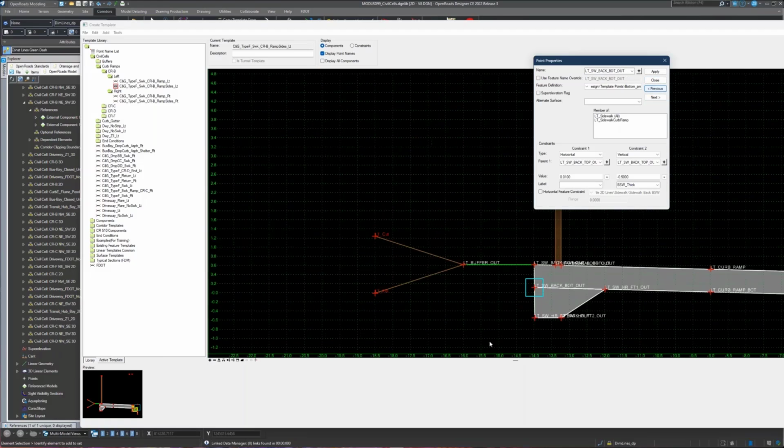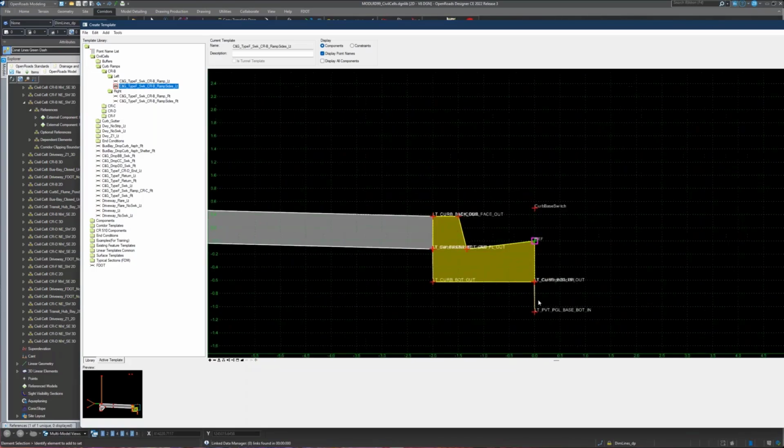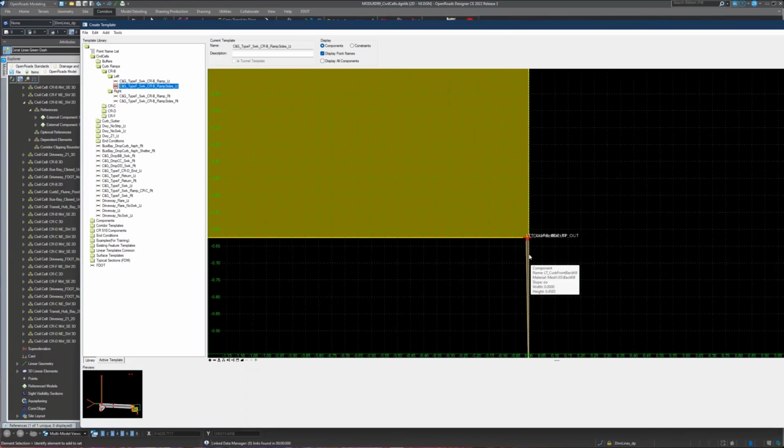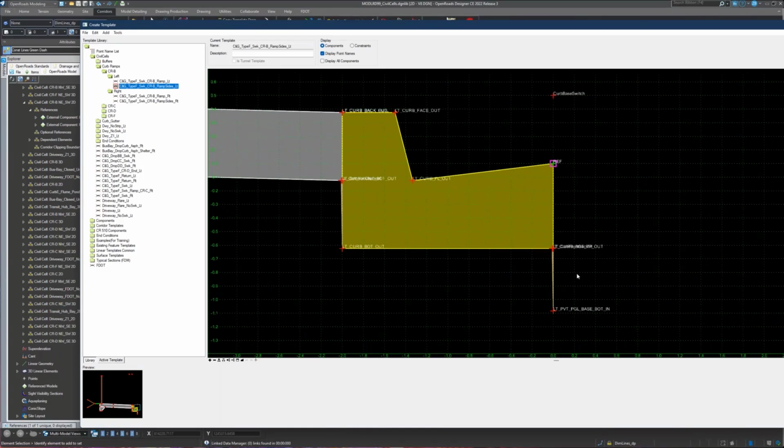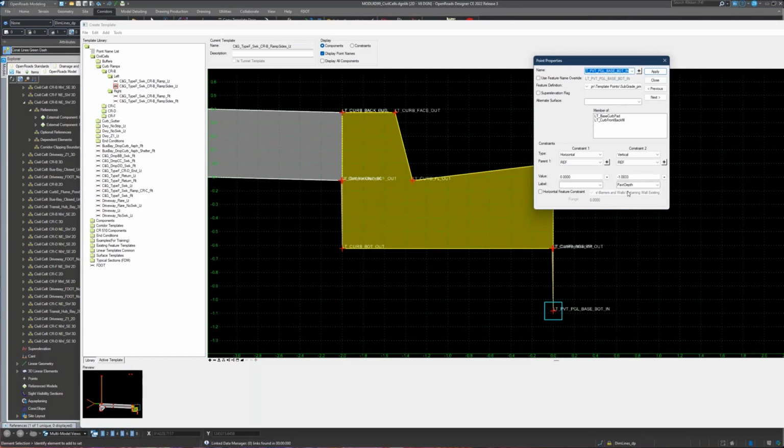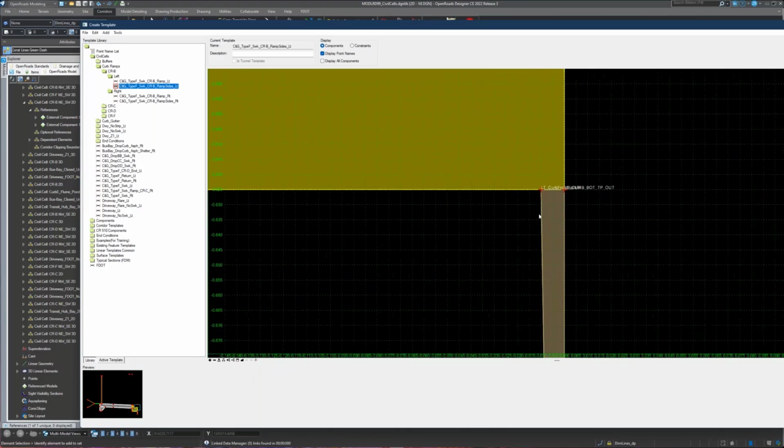And then you might have noticed I've got these other weird elements over here. I would call them backfill components. This is something that FDOT has taught before as well, is to use these backfill components. So what I've got here is this would be the bottom of your pavement. I've got a label in here that you can use to do your pavement depth. That's a parametric constraint you could add and set to your pavement depth, because obviously it's going to change depending on which project you're working on. And it's just this little tiny sliver.